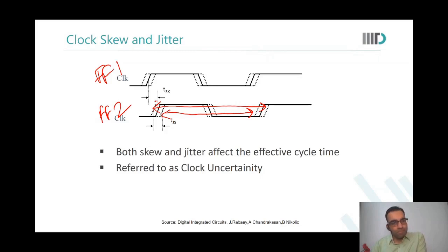And sir, I can see that the skew and the jitter are very unpredictable. And whether it will be there or not, I cannot definitely say. But skew is more deterministic. Good, I'm so happy that you're arriving at this deduction. But then how will we account for the jitter? That would be very difficult. We have to leave margins. Yes, sir, we have to leave the margins.